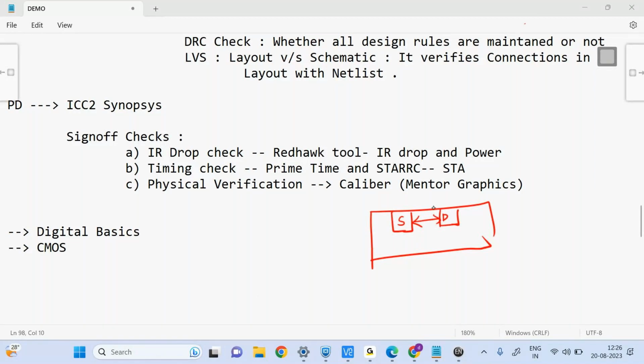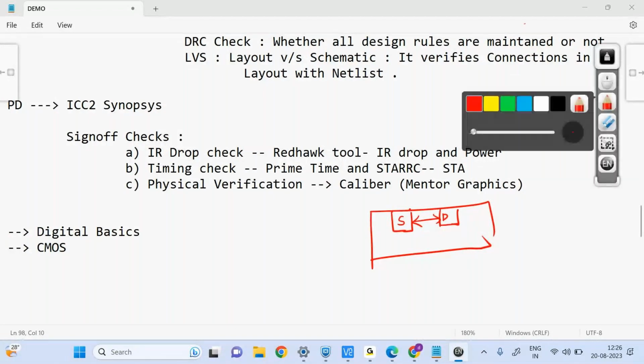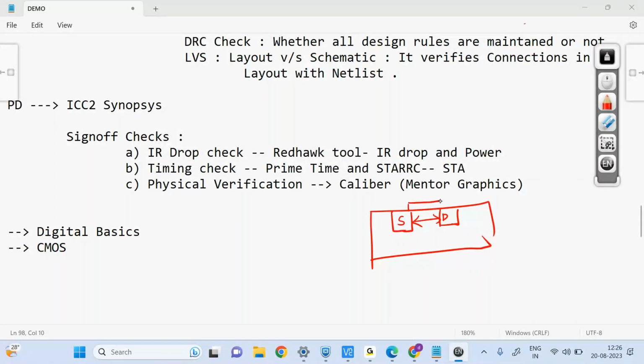See, this distance between source and drain is called the technology. 14 nanometer technology means the distance between source and drain is only 14 nanometer. If the source and drain come very close, the problem is you have silicon dioxide here, and on top of it you have the gate. When the gate voltage is more than the threshold voltage, only then we say the MOSFET is on, and current is flowing from source to drain.